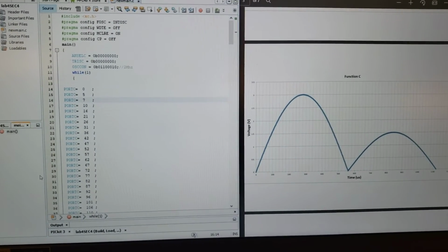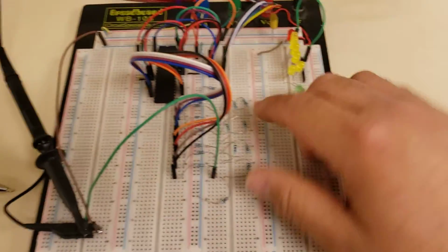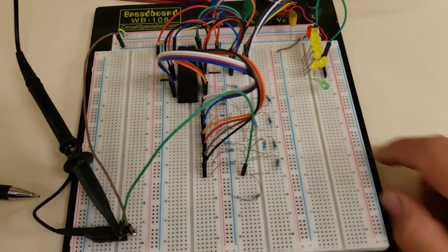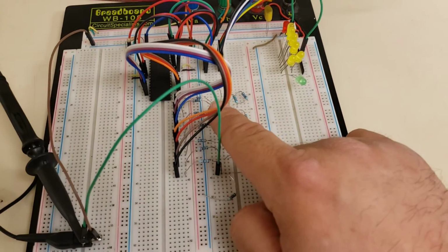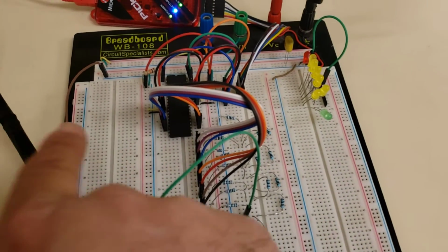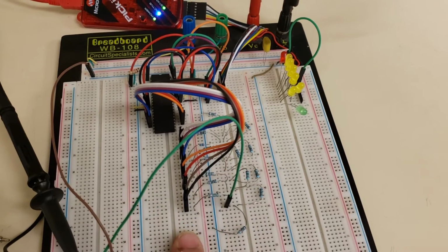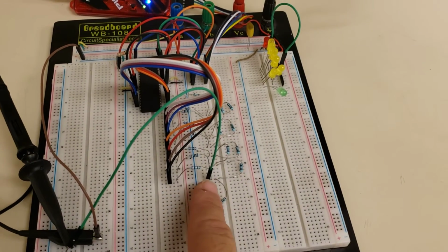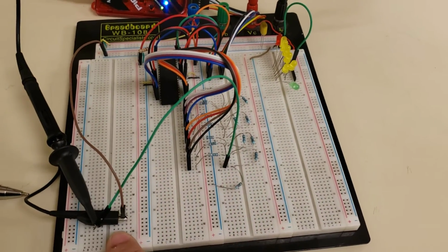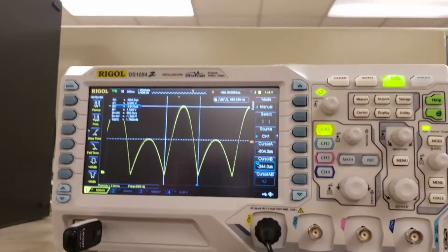We are taking these analog values and running it through our digital analog converter here. It takes advantage of the R2R ladder system coming out of our microcontroller into the digital analog converter. It comes out through our output, and we're measuring it with the oscilloscope.